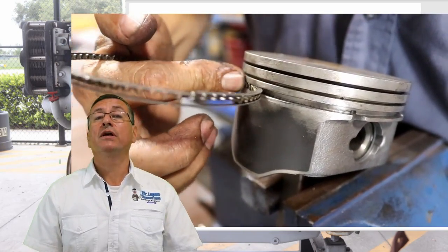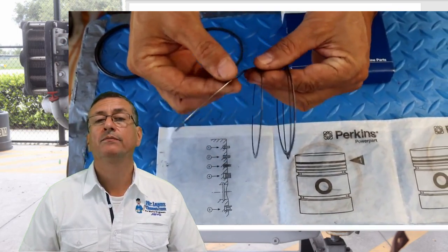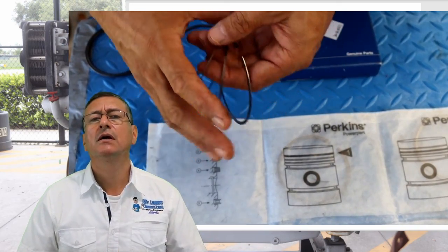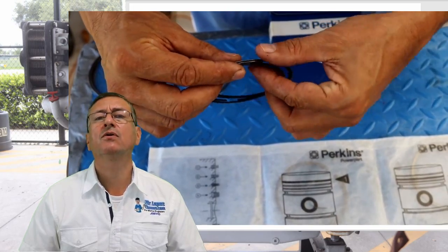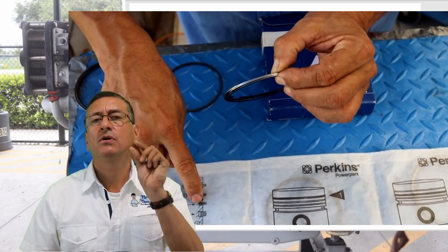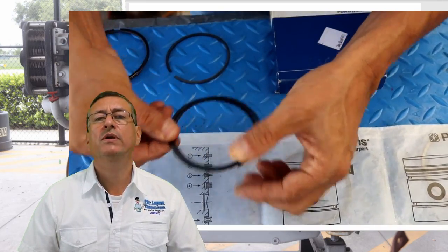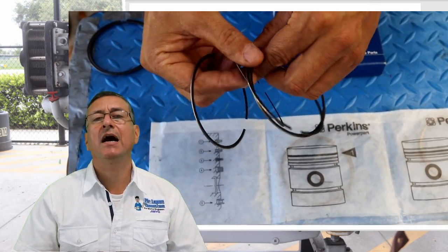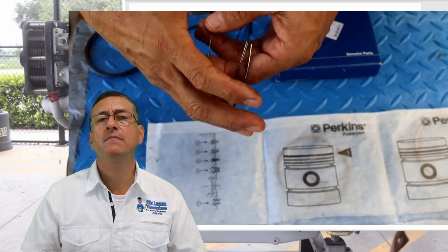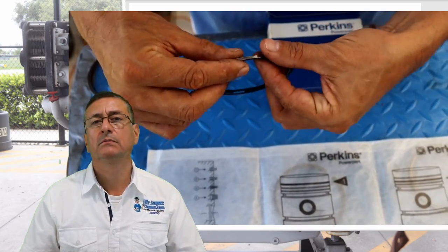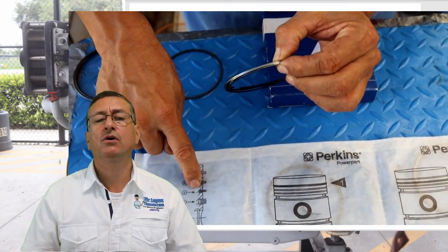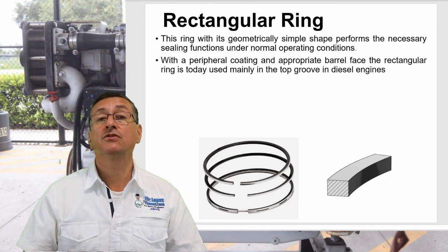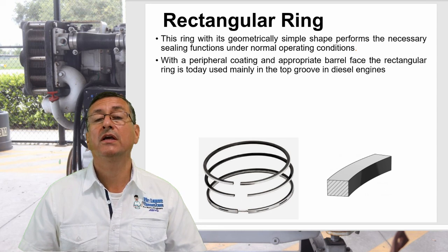There are other engines with 3 or 4 small thinner piston rings located in that groove. The 4 thinner piston rings enter in that groove, and they have a lot of space, and they allow the oil to pass in between them and return into the oil pan. This is the situation with those oil controller rings located in the third groove, and in some cases in another groove at the bottom.